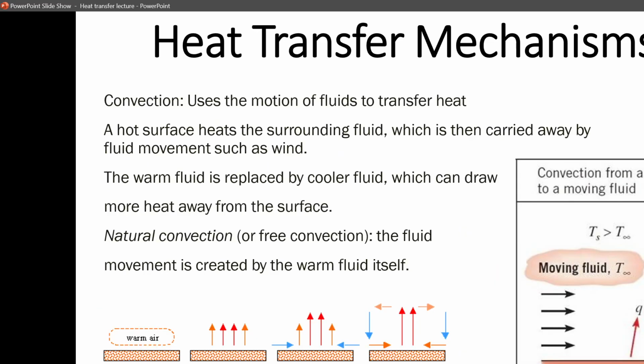So the other mode of heat transfer that is of interest to us is convection, which is essentially heat transfer through the movement of the fluid. Two different types of convection heat transfer. One is diffusion, where a high energy molecule moves to a lower energy area and stays there, which essentially will make the lower energy area a higher energy area. And another mode of convection is called advection, where a bulk of higher energy fluid will replace a bulk of lower energy fluid. So two different mechanisms for convection: advection and diffusion.